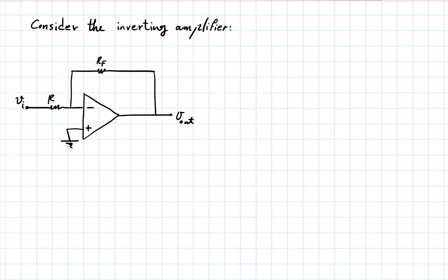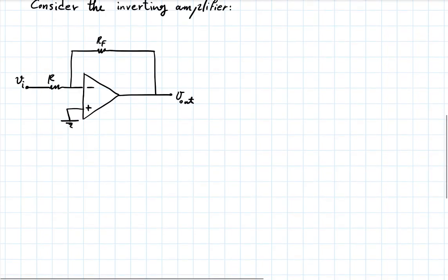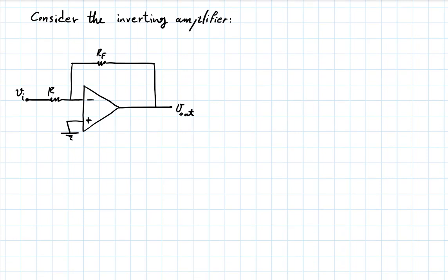And this is really helpful knowledge that we use to solve circuits like this. For instance, we said here we could solve it very easily by saying if this node is connected to 0 volts, your ground, so is this one, because the two input nodes should have 0 voltage difference, and therefore there is this current, which is simply V I over R, which then continues here, because there's also zero current going here, as well as here.